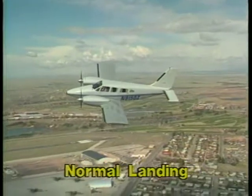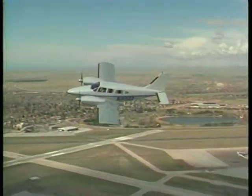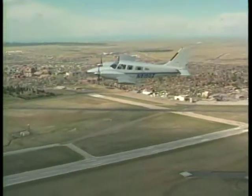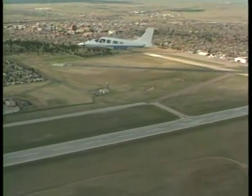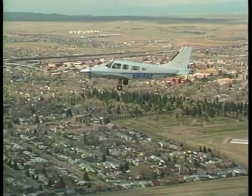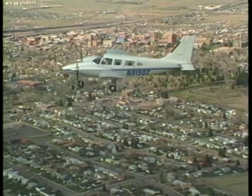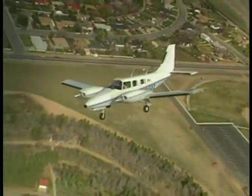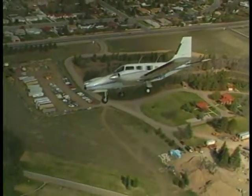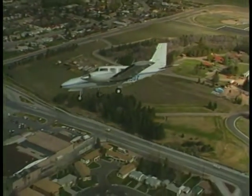A common technique for a normal landing in a multi-engine airplane is to use a stabilized power approach, where the power is adjusted to a specific setting just before pattern entry. The drag created by gear and flap extension slows the airplane to pattern airspeed and helps keep power adjustments to a minimum throughout the pattern. You may also need to adjust your airspeed for compatibility with other traffic, but don't reduce it below VYSE. In no case should you allow the airspeed to go below VMC.